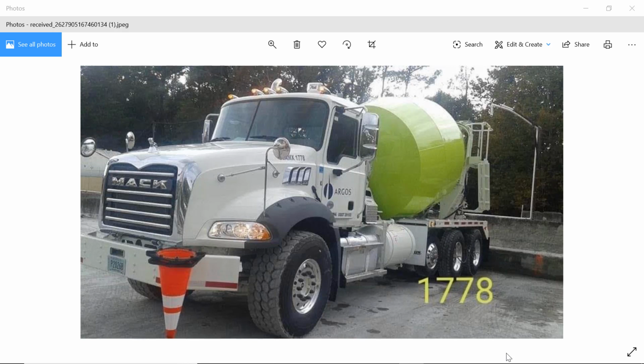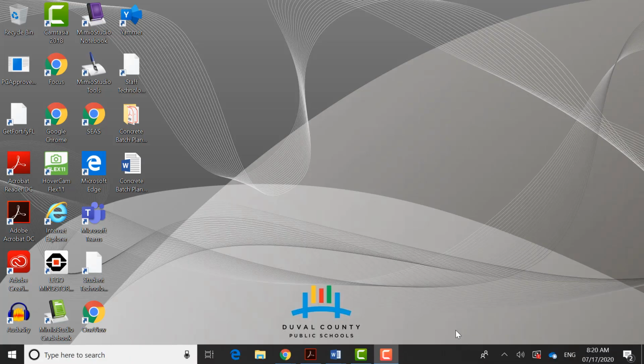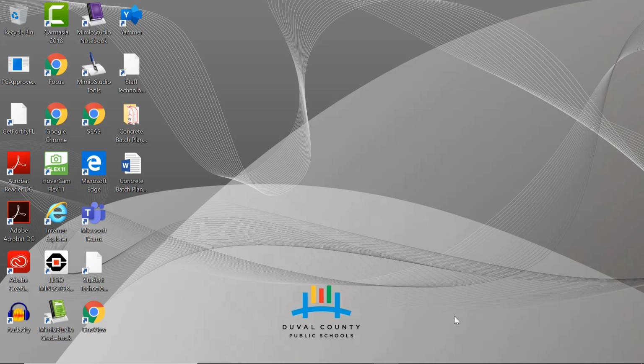Example 8. The example design mix contains 545. Example 9. A 5 cubic yard batch is called for that requires 685 pounds per cubic yard cementitious and a maximum water cementitious materials ratio of 0.39. It is to be batched to allow 15 gallons of job site allowable water addition. How much water per cubic yard should be used in the initial batching?